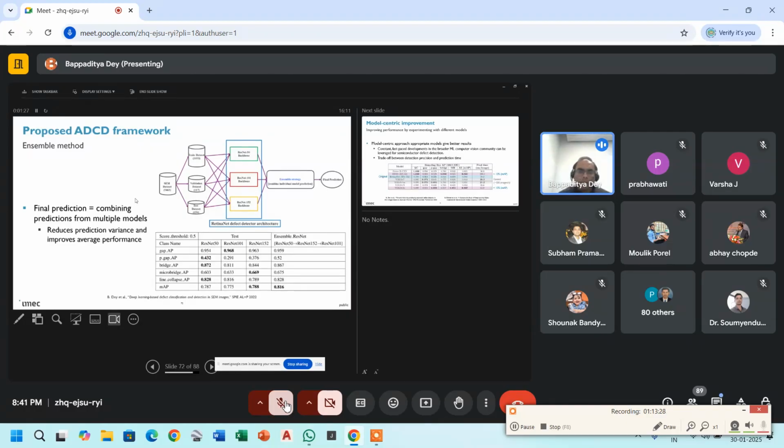I'm taking the ResNet family, 50, 101, and 152. Okay, I have 5 different defects that you have already seen. And now if you see the performance, and the overall performance, I have 78% for ResNet 50, 77% for ResNet 101, and 152 is 78%, say. And you can see that for some of the defects, it is performing really, really poor, right? For ResNet 101, for probability of gap, that means when your metal line is becoming narrowing down, it is only 29% or 37%.